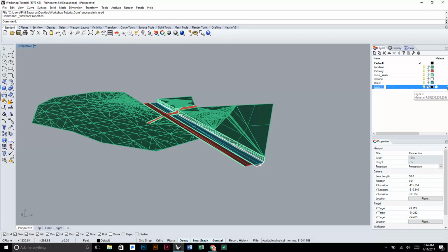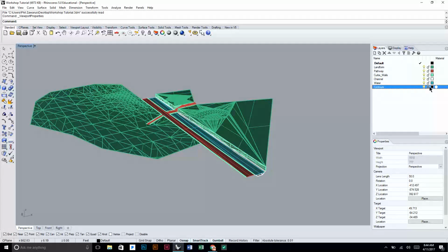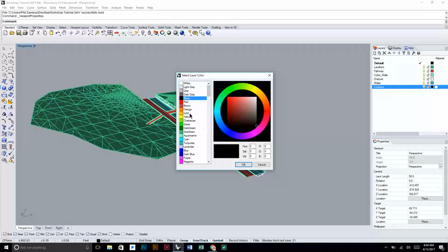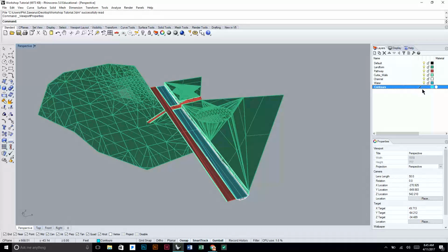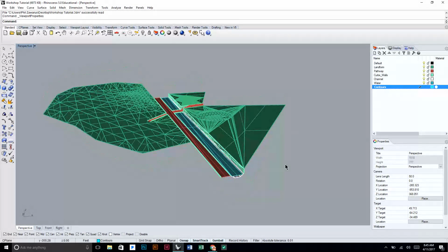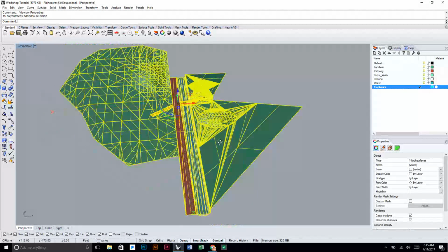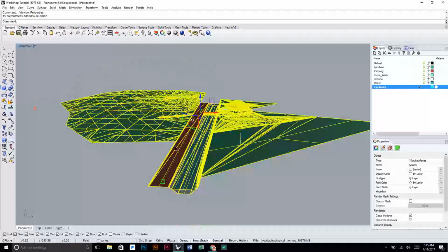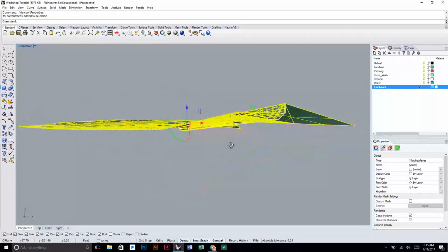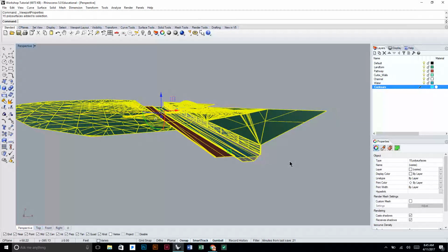So let's just go ahead and create contours. Let's find something that'll work good with that. Green. So I'm going to make that my active layer by making sure that it has that check mark. And now I'll just select everything because I want it to actually run a contour through all the objects. What's nice is you can have the contours go through just one object type or everything that's selected. So right now I just wanted to do a contour for everything. So I'm going to type contour, real surprising name right there.